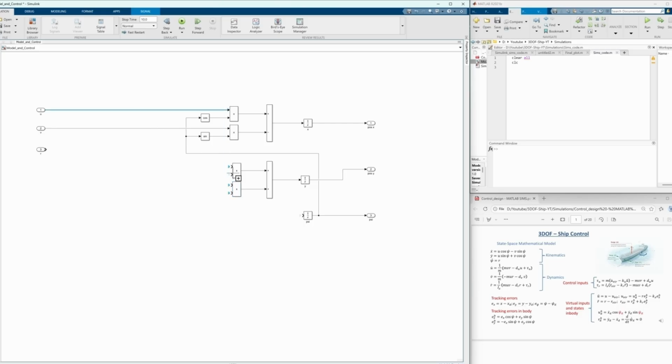So you click over here. So this comes over here. And then we have sine psi. What I can do is put a sine block over here and do the process again, similar to the previous one, sine, and then connect this over here. But just to make it simple, I will directly take the pin from here because I already have this sine psi over here.